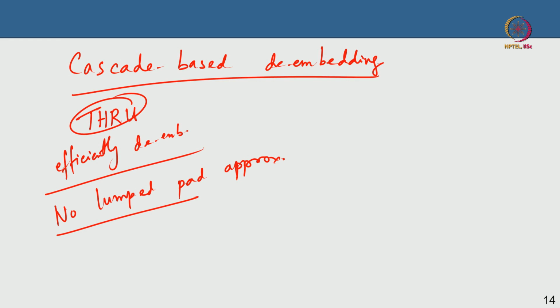So what you do first, if I talk about a CMOS-like thing, for instance, is I have a ground pad. The ground pad you don't have to metallically connect to the active device because it's connected to the bottom of the substrate, say for an LDMOS. So it's like a default via hole. So this is your ground.